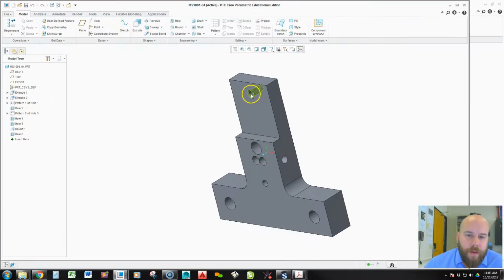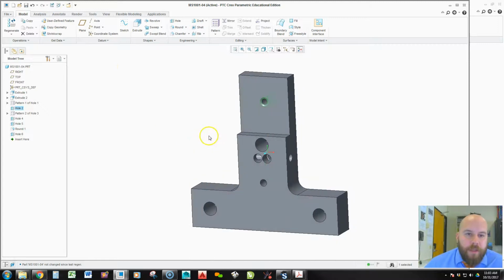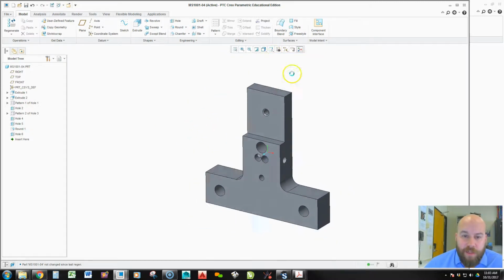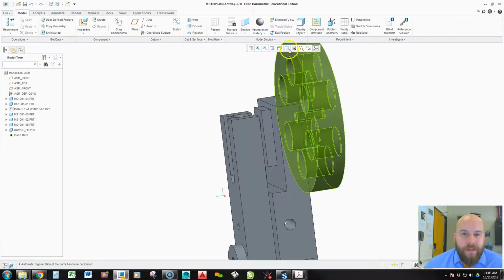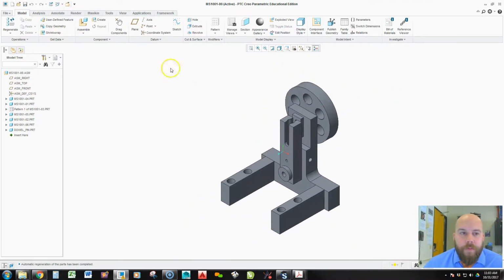If you model things properly, it really shouldn't matter either way. Okay, if you spend some time paying attention to how am I modeling this, what's the orientation. Notice the orientation of this part when I modeled it, it's exactly the same as it was in the assembly. And considerations like that can save you a lot of time down the road.